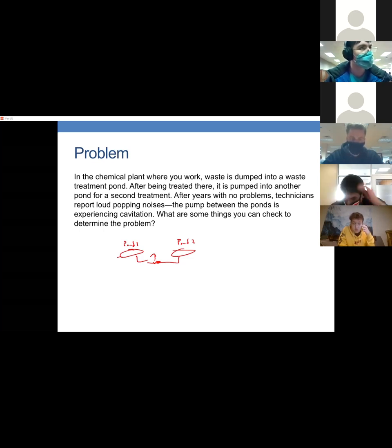Other things, I suppose it could have gotten hotter. Hopefully you should have designed your system to account for that, but maybe if it's a once in 100 years heat wave, you might end up getting cavitation when you hadn't before because you just didn't design it for that high temperature.